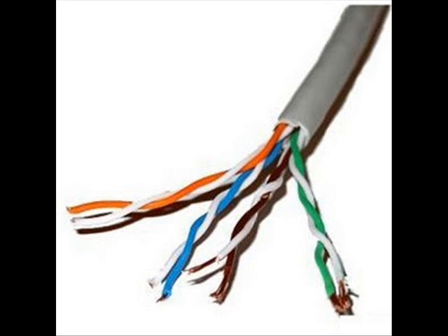Electric current going through any wire causes a small magnetic field. That field interferes with adjacent wires, causing crosstalk. To help solve this issue, twisted pair cables use two wires in the same circuit twisted together so magnetic fields cancel each other out. This combination also protects them from some outside interference. There are two designs, unshielded and shielded.